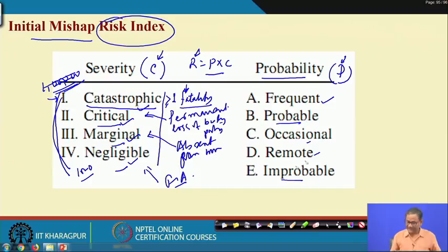But in qualitative risk assessment, please understand that for the severity scale as well as the probability scale, there is no reference point. It is basically used for ranking purposes. So, for my own system, considering all hazards, if I stick to this, then when I compare the first hazard's risk with the second hazard's risk, the difference will be significant, not the individual value.